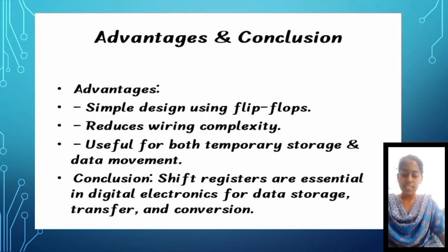Next, advantages. Shift registers have several advantages. They are simple and easy to design using flip-flops. They reduce hardware requirements in data transfer. They can be used for faster data storage and retrieval. They also help in saving communication lines by converting parallel data into serial.